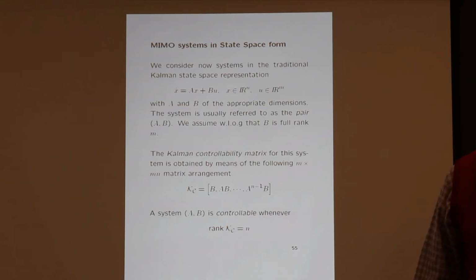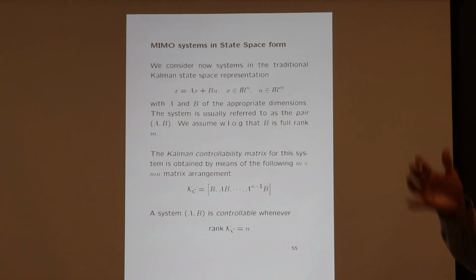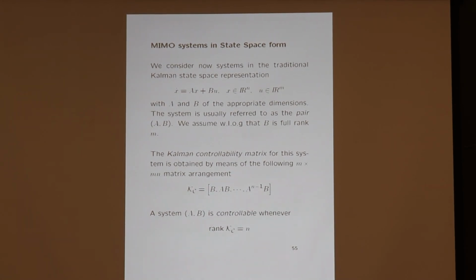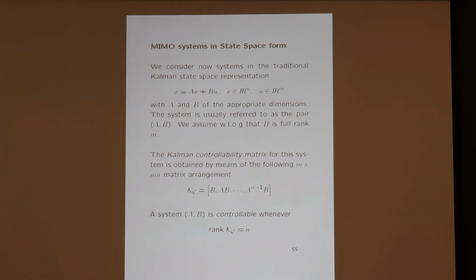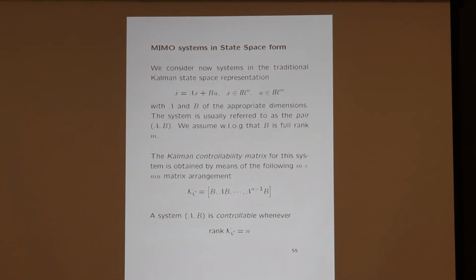And now we get to the state representation. I prefer to leave that for a next lecture, because that is the most important case. The other cases, the physical meaning is not so clear. That's true, but it is useful to know that in those representations the zero dynamics is very well hidden, and in order to extract it you have to know about the poles and zero definitions for this class of systems. And this factorization is not always easy to obtain.